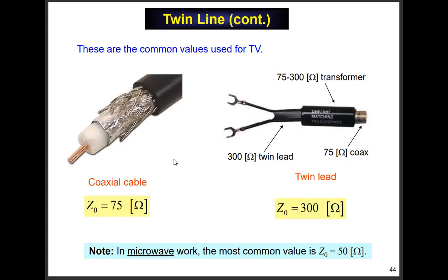Now, by the way, what's so important about this characteristic impedance number? We're really going to see that in note 7, but I'll just give away the secret. When I have a transmission line coming down and meeting a load, the load could be a receiver, it could be your TV set or something. You want all the power in the signal going down the line to go smoothly into the load, right? Into the receiver. You don't want reflected energy because it's wasting energy.